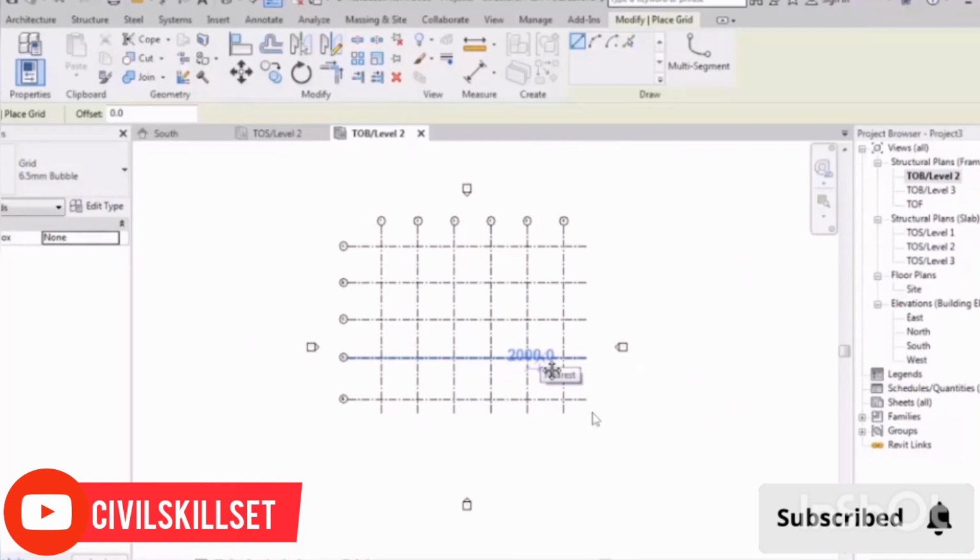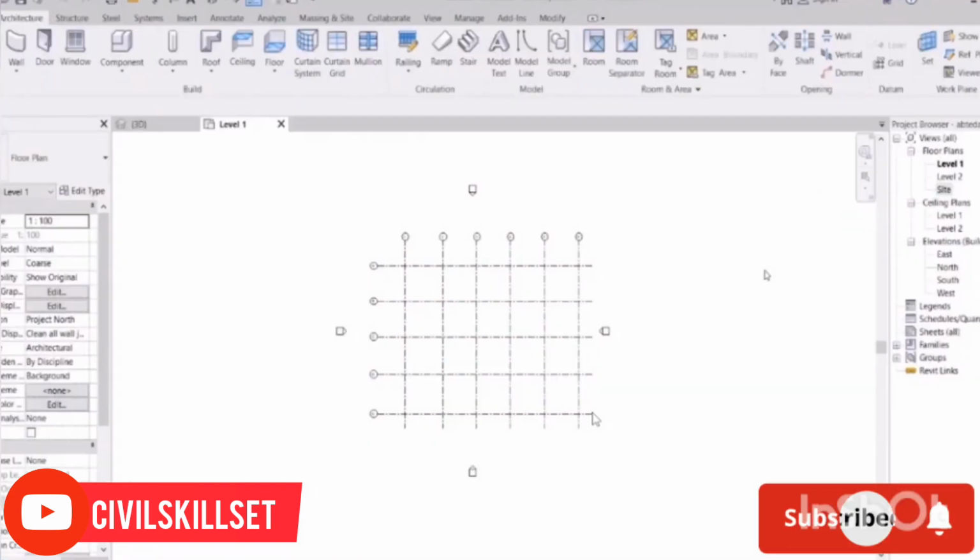Again, the same thing. So this is everything about designing, but a very important point here, I've always said that the 0 of the project should be in a specific spot and a constant spot. And in big projects, it's already told you officially that this is the 0 spot and all the groups will work based on that. And if you remember one of the projects, where the center lines had crossed, we considered it to be 0. Now, in phase 2, at first the structure is prepared and then the other groups will import it and start working on it.